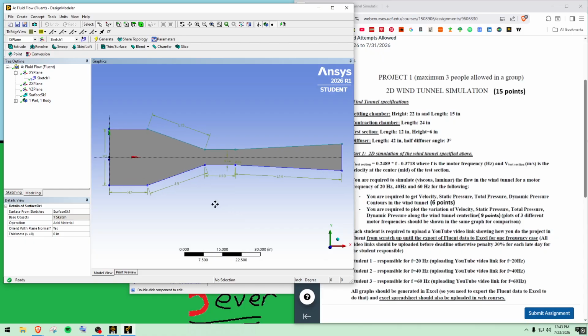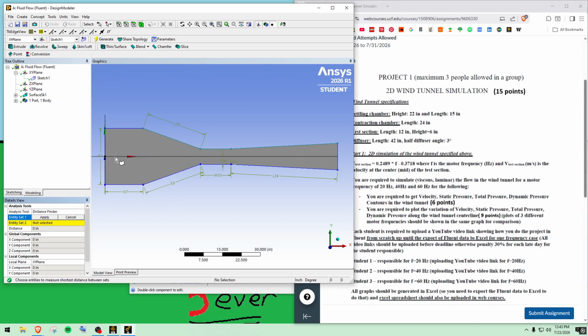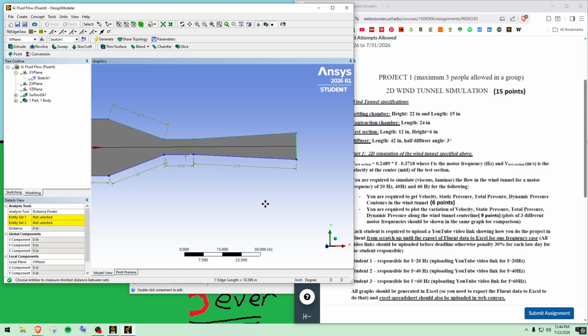Alright, so I'm just gonna skip ahead a little bit because for our later steps we're gonna want our midpoint. So what I like to do, I'm gonna hit tools, and then under analysis tools, distance finder. Oh, not that, cancel. Let's see if I can do it. Oh, well, yeah, you want to do your edge select up there. You're gonna hit our inlet and then our outlet.